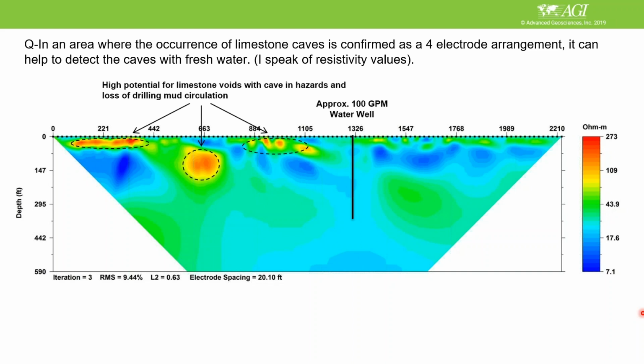Okay, soil resistivity question: temperature. We don't measure temperature, but temperature does affect your resistivity values, yes. This is important when we're not talking about surface temperature, but about the inside of the ground.